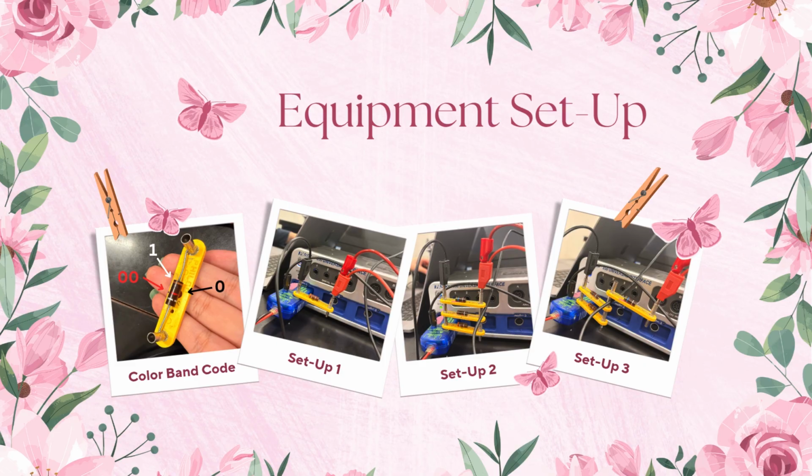Black is 0, brown is 1, red is 2, orange is 3, yellow 4, green 5, blue 6, violet 7, gray 8, and white 9. For setup 1, we tested how one resistor is connected, in setup 2 we saw it in parallel form, and in setup 3 a combination of both parallel and series form.